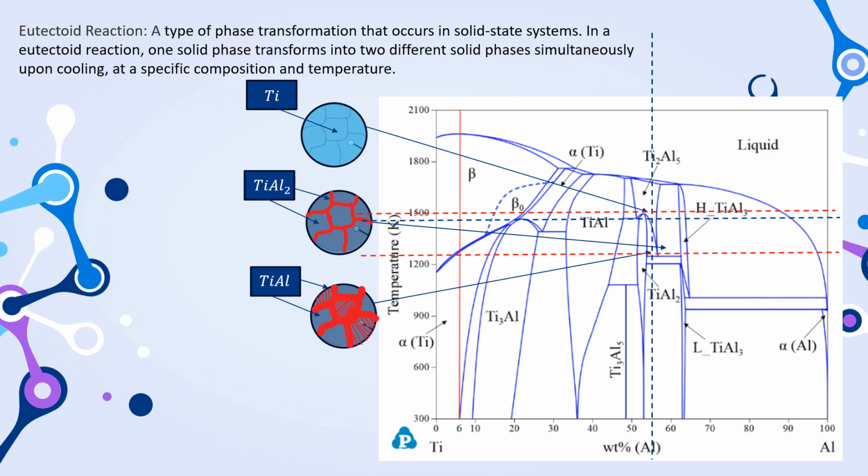tetragonal structures. To use the lever rule, we take the value of x_s and subtract the total length of the line. We then divide that all by x_s minus x_l, getting us the mass of the liquid. To find the mass of solids, we change the numerator to the total length minus x_l. Doing this, we find that m_l is 50% and m_s equals the other 50%.